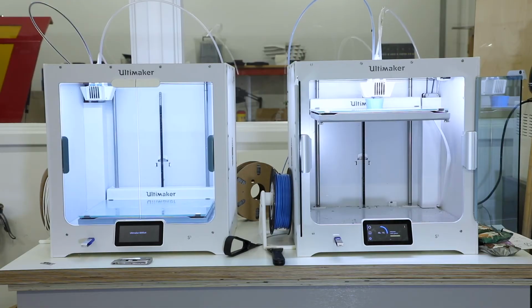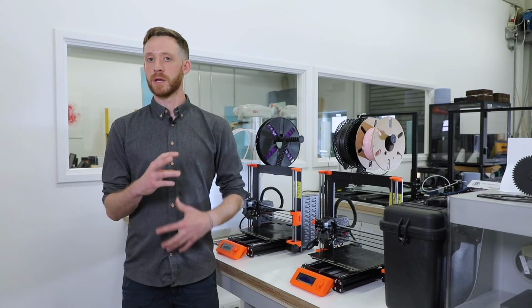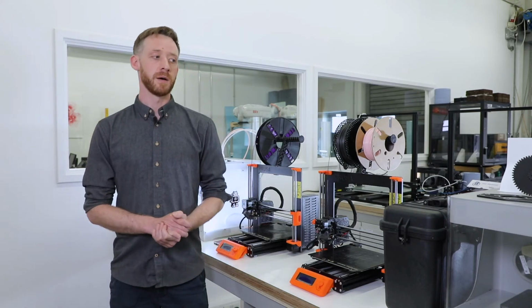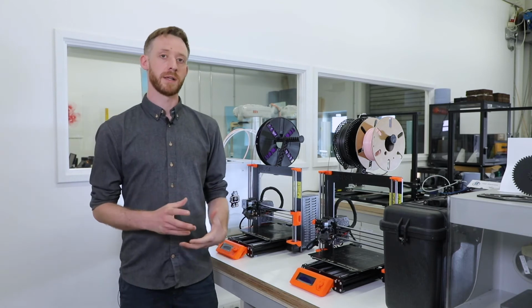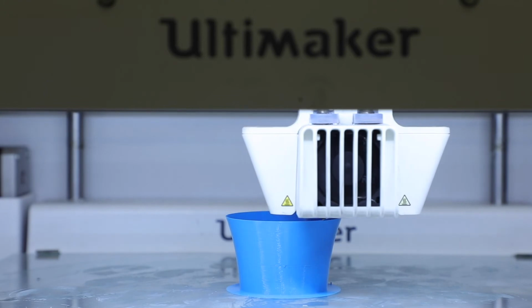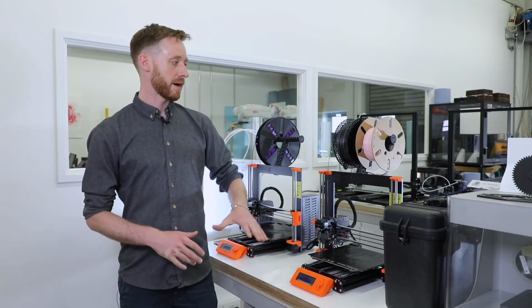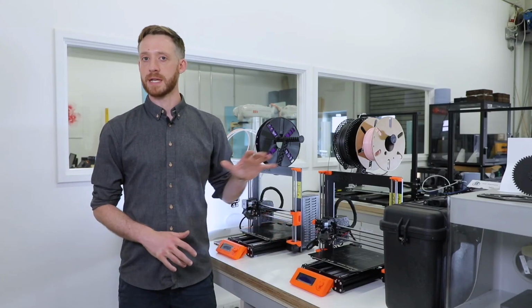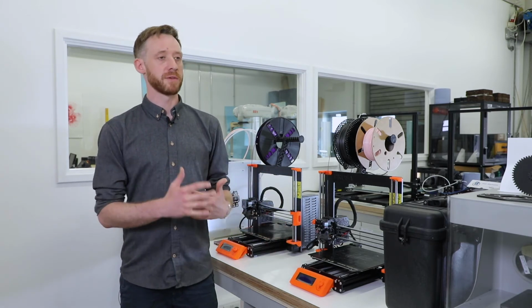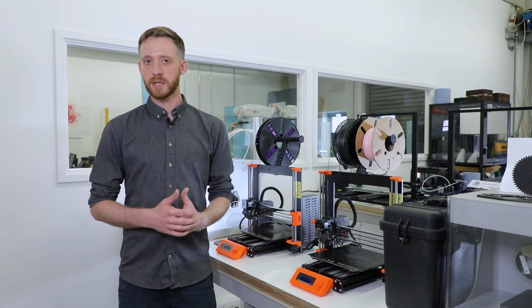The workflow to get there is a little more complicated, but you've learned all the foundations with the laser cutting. And with 3D printing, we can work at different scales and with a lot of different materials as well. Starting off, we have very simple bioplastics. It's very easy and quick and cheap to print with. The resolution of that is about 0.2 millimeters.